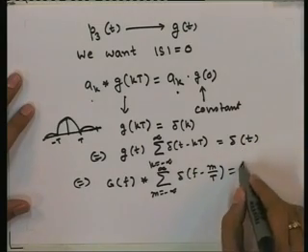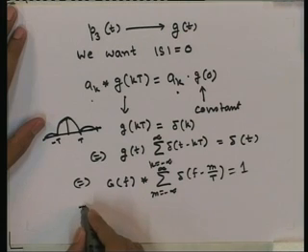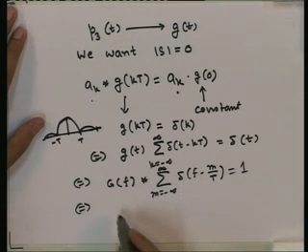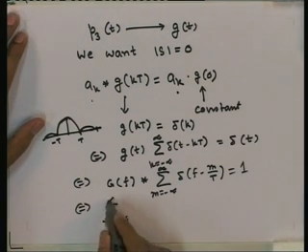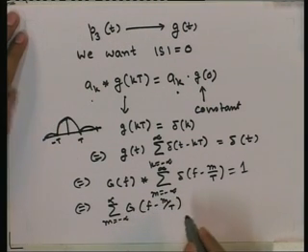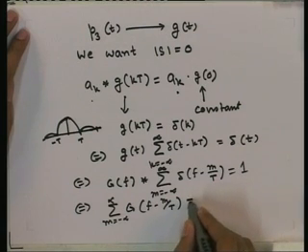So at multiples of 1/T frequency, there is a delta function. That is the Fourier transform of this. And what is the Fourier transform of delta(t)? This one. So now if we take the convolution of G(f) and delta(f - m/T), it is G(f - m/T). These are all standard results from Fourier transform. This is one.